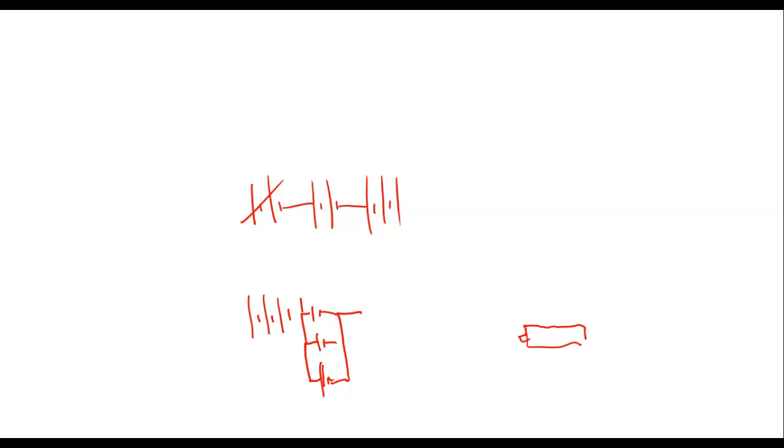So when we say we got 6 cells in there, that's not exactly true. You got a bunch of cells. If you ever looked at the plates in there, it's got a bunch of plates, then it's got a bar across the top of it, so that's in parallel, and then you got it running to the next set of cells. So how much current you get out of it would depend on how many of these things you could get in parallel, and how much voltage would be how many they could hook in series. And this is why usually the bigger the battery, the more current you can get out of it, even though you've only got 6 cells.